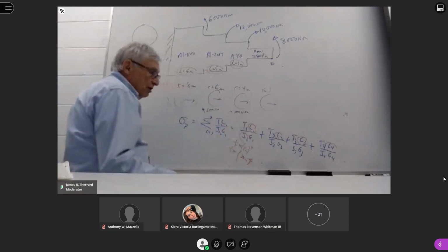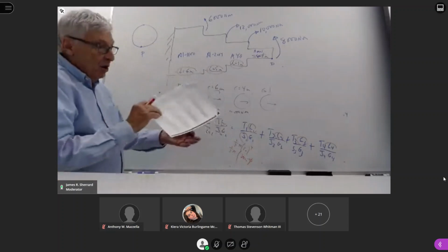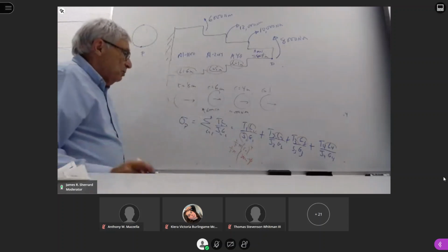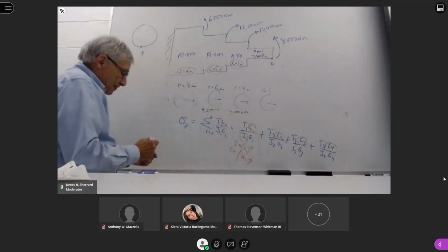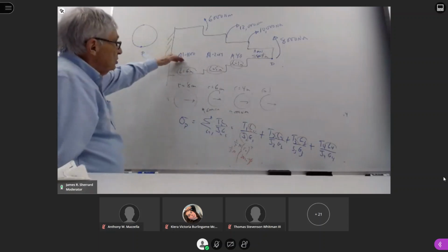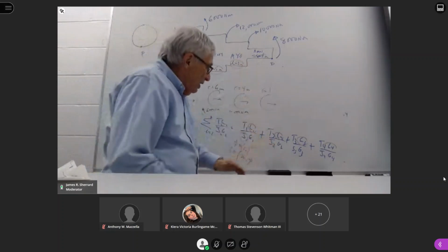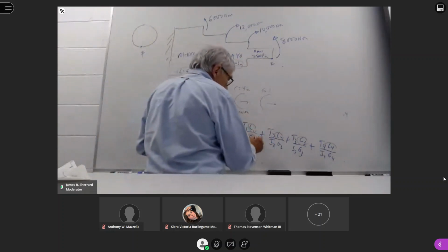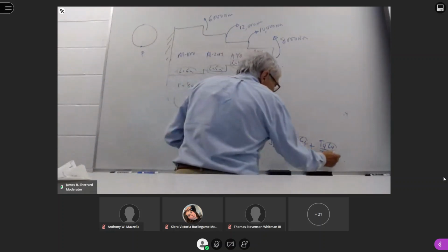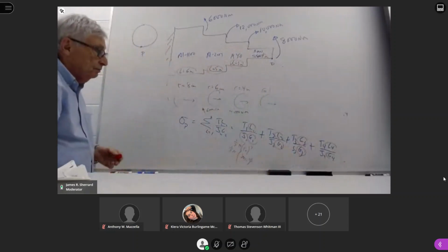G is the modulus of rigidity. We'll find that on the table that I gave you, depending upon what the material is. So each one of these, this aluminum, this annealed yellow brass, and this stainless, will have their unique values for G that you would put in.